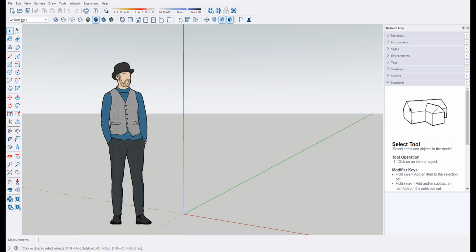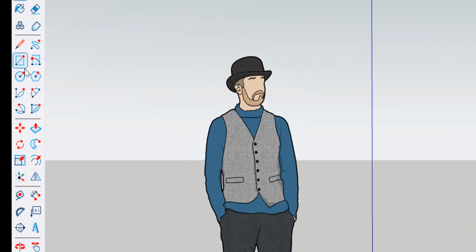I'm also going to focus in the lectures on the keyboard shortcuts because sometimes the location of the icons changes, sometimes the images change, things like that, but the keyboard shortcuts usually stay the same from version to version. And I would recommend that on any CAD program. So we'll start with the rectangle tool. It looks something like this. And notice that the icon itself kind of hints at what you'll be doing. It shows a rectangle being made by 2 points, a start and an end point, diagonal from each other. That's how that tool works.